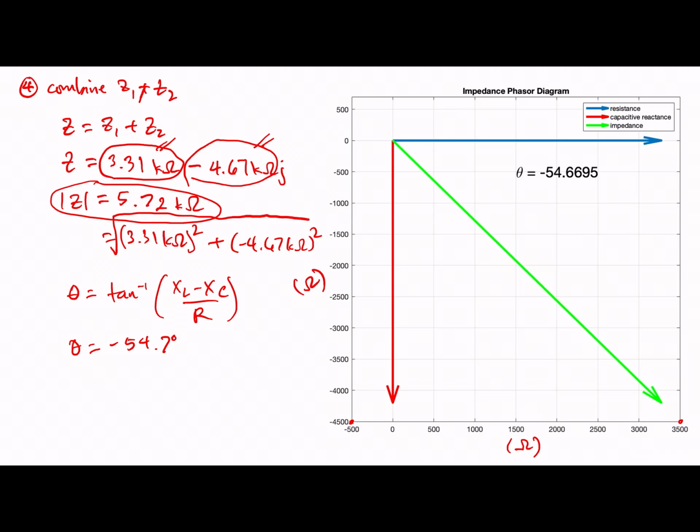And the reason for that is that in MATLAB I'm using a command called quiver, and quiver draws a vector, but it does not draw the whole magnitude of the vector. Because graphically you draw multiple vectors and you don't want all those vectors to touch from head to tail. So this is why the length of the arrow does not correspond to 3.31 or 4.67 as it should, and that's only because the quiver command does not draw the arrow to its full magnitude.